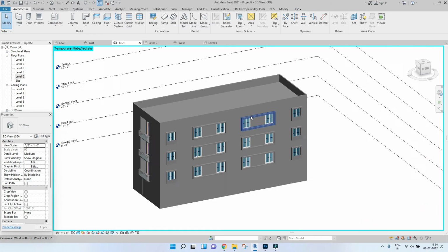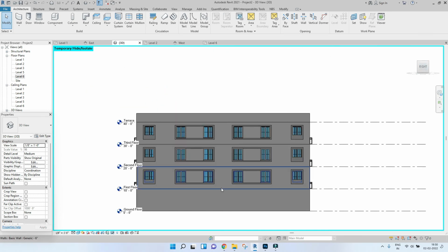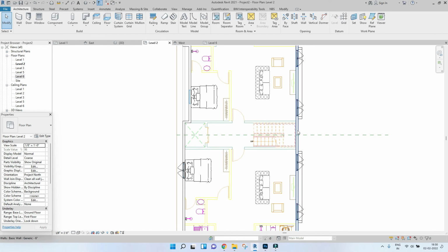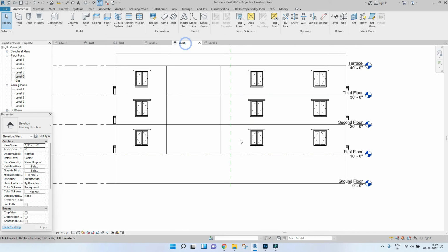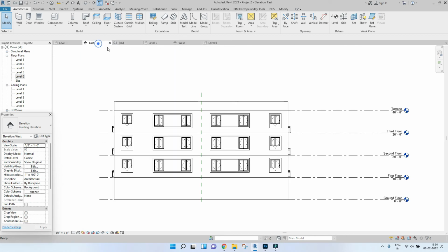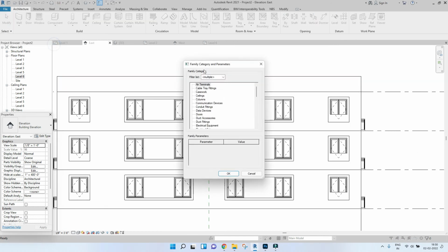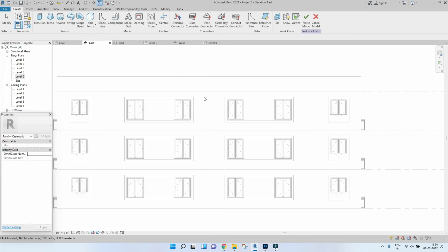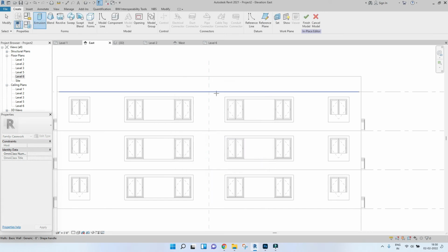Now I just want to add a big casework in front of the building, like over here. So this space is basically where all of the stairs are. Instead of this, in front of these stairs, I just want to add a casework. So to do that, go to east, go to component, model and place. So this is another type. This is a much more complicated one. So let me show you how it's done. Go to pick a plane and pick any of these walls.